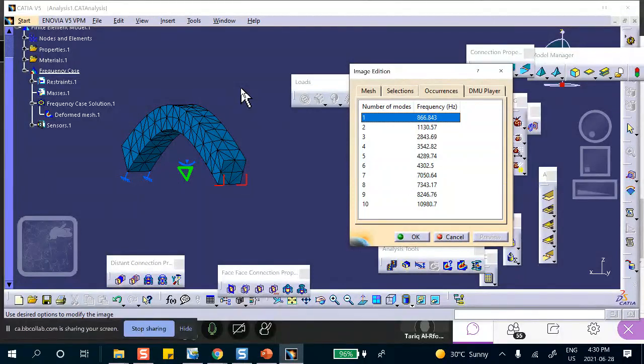But isn't it safe to be above or below the natural frequency? Yeah, you're right. But when you turn on the fan, let's hypothetically say the fan goes to 1,000 RPM. Okay, that's a big figure. At some point, it starts from zero and it has to go through that frequency, does it not? At some point, it'll go through that speed to get to 1,000.